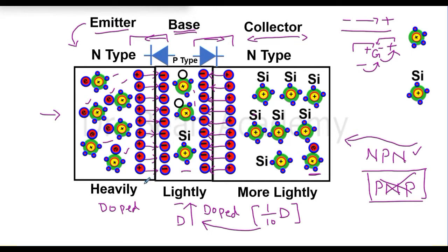Or I can make this one reverse bias and the next junction forward bias, or in the third case I can make both reverse biased, right? So I can make both junctions forward biased, both junctions reverse biased, or one forward bias and one reverse bias. So there are many possibilities, and I will explore how we can do that.